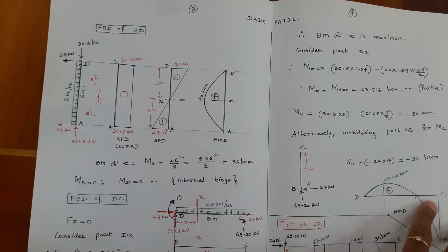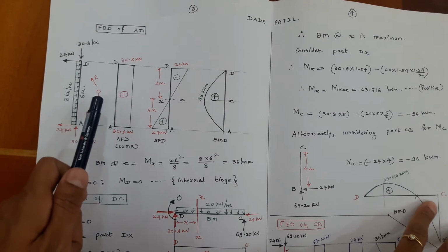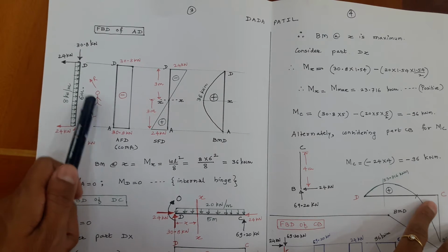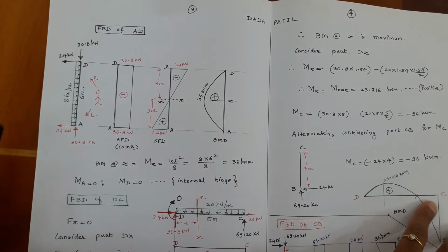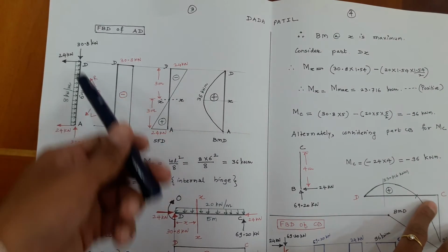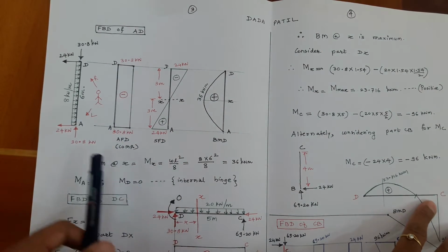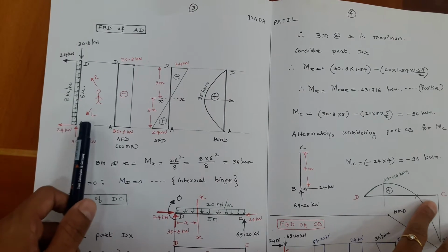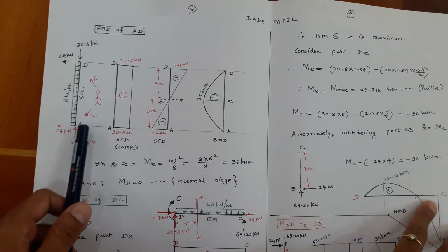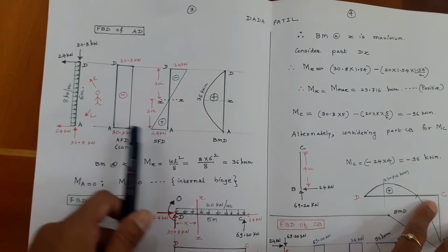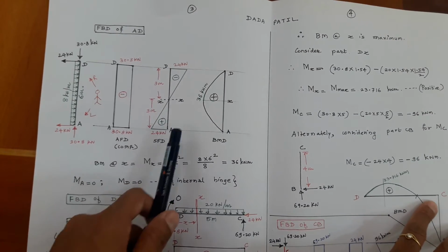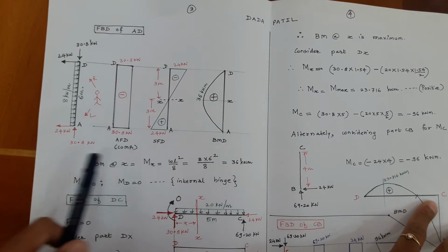Now, coming to the shear force diagram, the simple way is to always stand inside the frame and look towards the part whose SFD you want to draw. So, automatically this becomes your right and this becomes your left. Again, due to 24 kilonewton at A, left is going up, and that I take as positive and I draw it outside the frame. So, it is 24 kilonewton, I have drawn outside and shown positive.